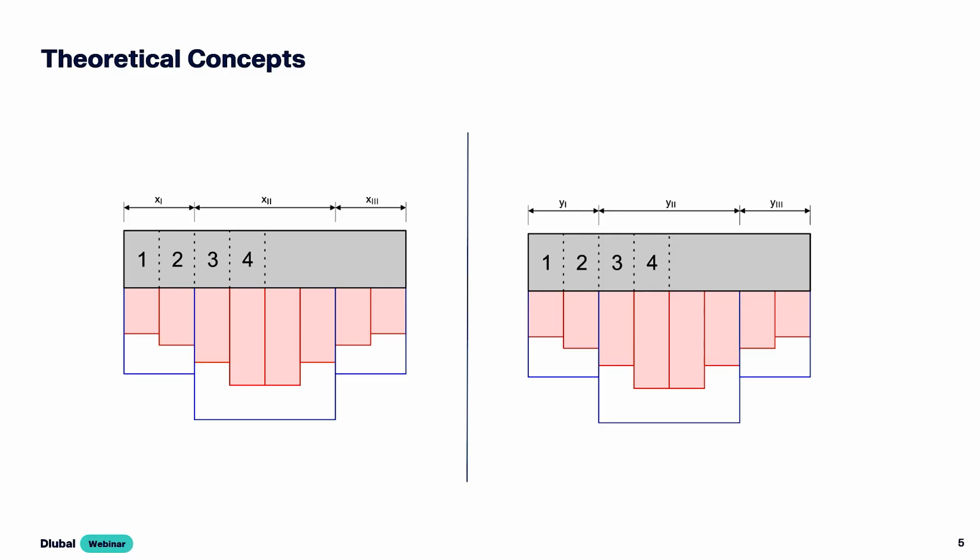So this slide shows a foundation in both the X and Y directions. The red line represents the moment distribution, and here the highest moment occurs directly below the column, while it decreases towards the edges of the foundation.